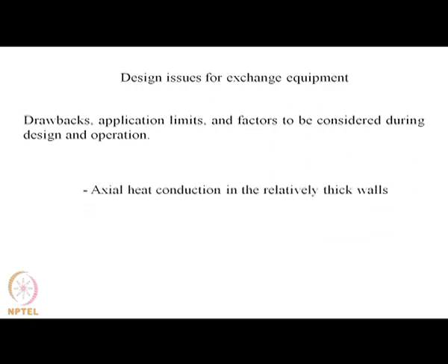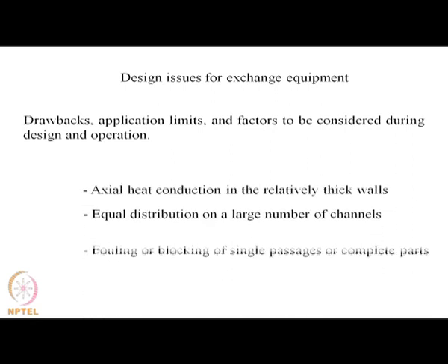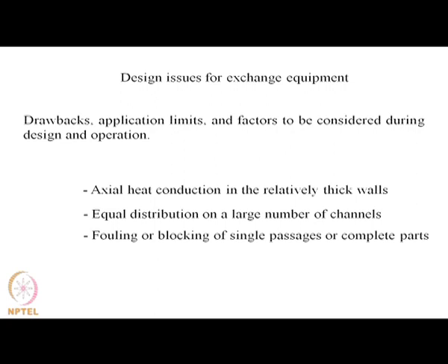And regarding the design issues for exchange equipment, when we consider heat transfer, it is the axial heat conduction in the relatively thick walls which reduces the delta T available, and if it reduces the delta T, then our process efficiency gets hampered. How do we distribute it equally in all channels?